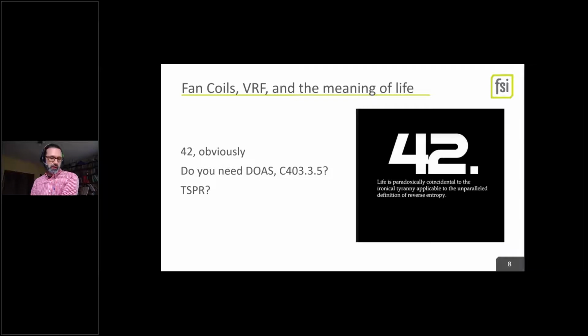So fan coils, we typically think of them as 4-pipe fan coils. I have a heating coil, a cooling coil, and a fan. And in some cases, an outside air intake, direct connected to it, or sometimes they were already set up with DOAS units. Back in the day, you might have had just a true DOAS unit, no return, no exhaust, no energy recovery. It just pumped 100% outside air into the building.